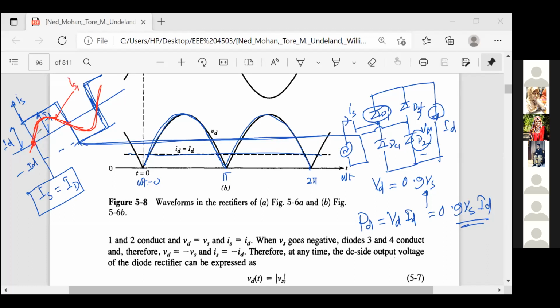So what is the phase difference? Let me also draw the voltage, input voltage. Suppose your input voltage will have the wave shape like this. The black color is VS. So now the zero crossing of the VS and IS1, is there any phase difference? No, sir. Zero. So we call it phi 1 phase difference, and it is 0. And cosine of phi 1 will be known as displacement power factor.